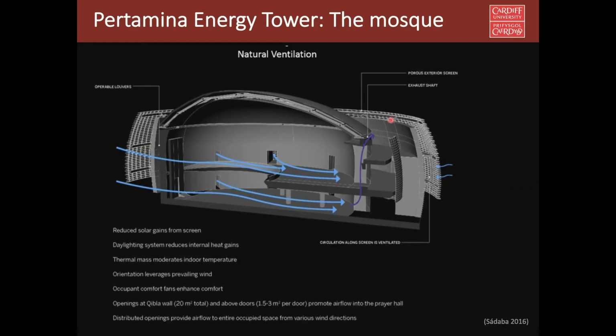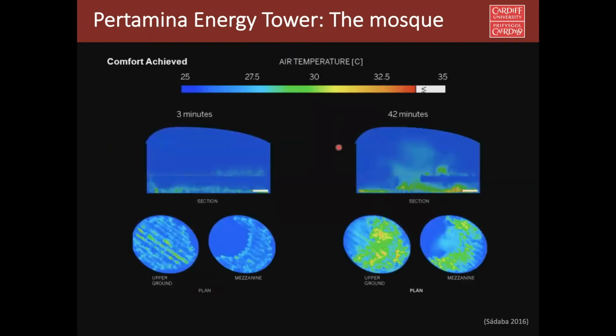And they see what happens if it is a free running building. This is the CFD simulation, and you can see the temperature distribution in the free running building. Sometimes the temperature is 32, but in many cases it's like 25 to 27. And according to SOM, in Indonesia, thermal comfort is still attained even if the temperature is 32.